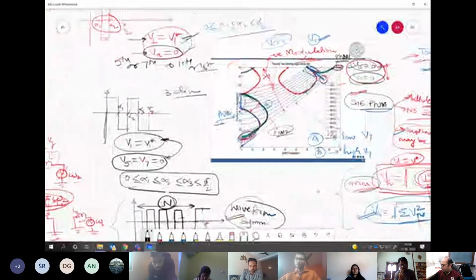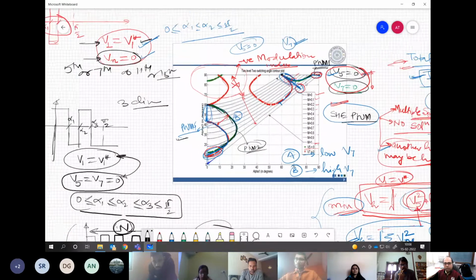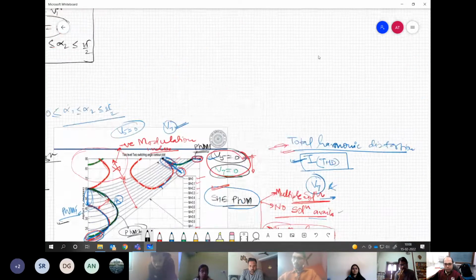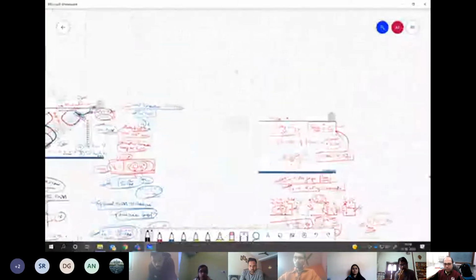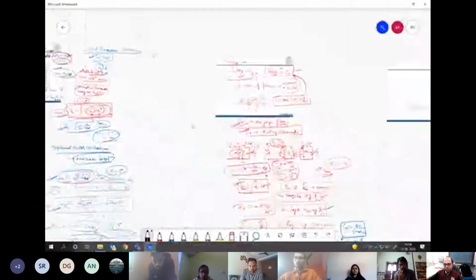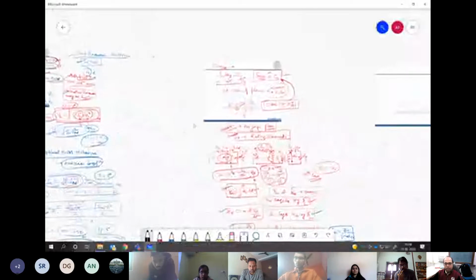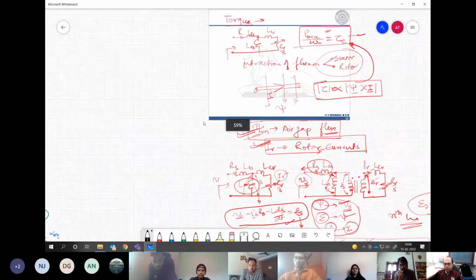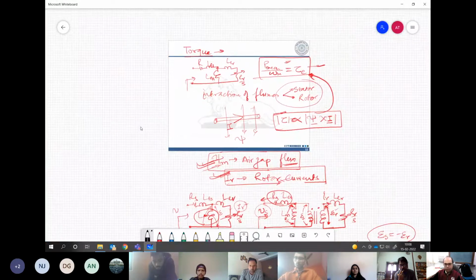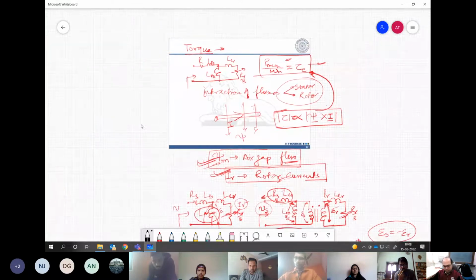If you look at the two switching angle case, here we have the contours plotted for different modulation index and different harmonics going equal to 0. So these cases we can understand. Based on our requirement, let us say we want to reduce a particular harmonic, or a set of harmonics, or the current total harmonic distortion, these things we can figure out.